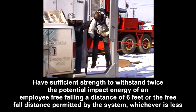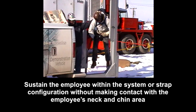Have sufficient strength to withstand twice the potential impact energy of an employee free-falling a distance of 6 feet, or the free-fall distance permitted by the system, whichever is less. Sustain the employee within the system or strap configuration without making contact with the employee's neck and chin area.